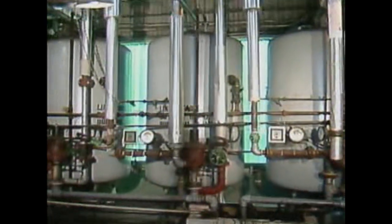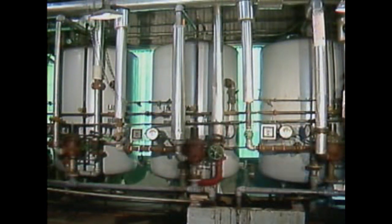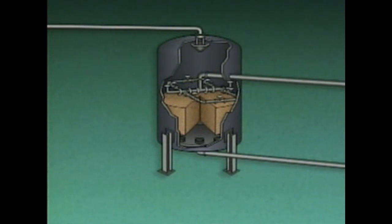Water is softened by a process called ion exchange. In a water softener, hard ions are exchanged for soft ions, such as sodium ions, which normally don't cause scale. This is an illustration of a typical water softener. It includes a tank or shell and a resin bed made up of small plastic beads called resin beads. The resin beads are porous so that water can pass through them.